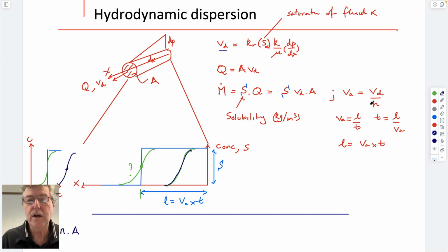All it is, one gives you the bulk flow, which is the Darcy velocity. The other one gives you the actual speed at which a particle of water moves. If you want to convert the speed at which a particle of water moves into the volumetric flow rate, you have to multiply by porosity, which I think is what you're saying. Yeah, but it'd come out the same either way, because if we're anything, we're consistent, and we're thorough, and we're correct.